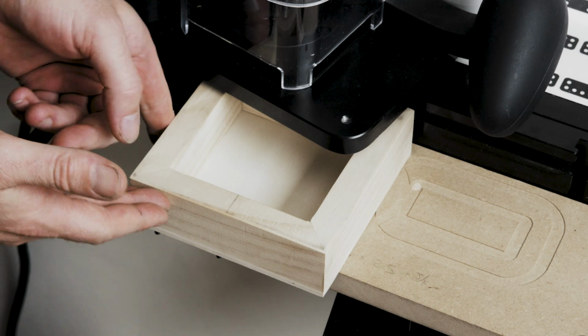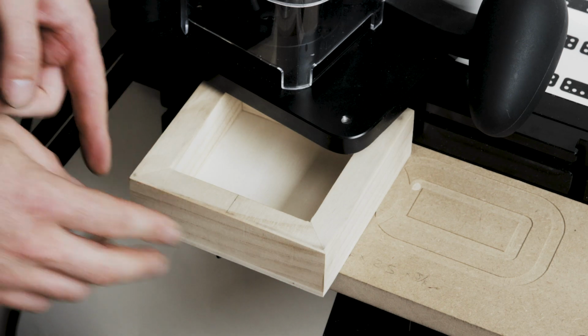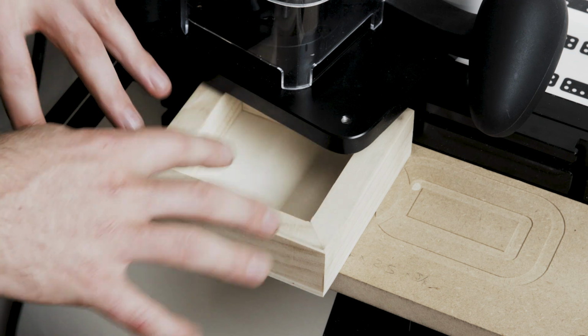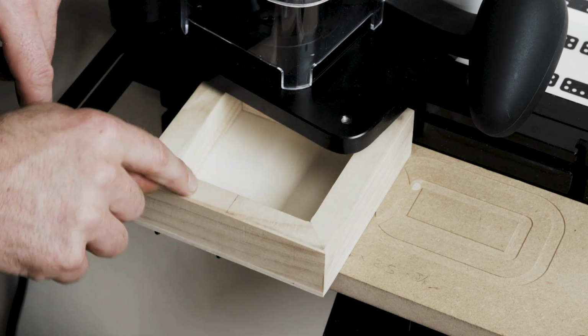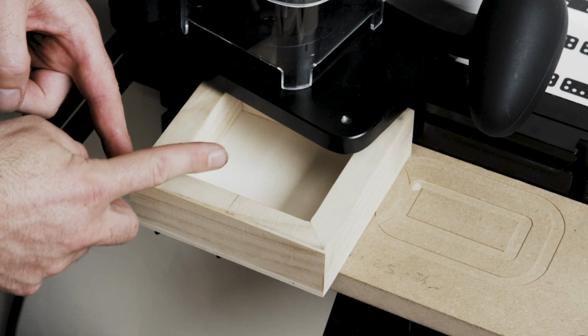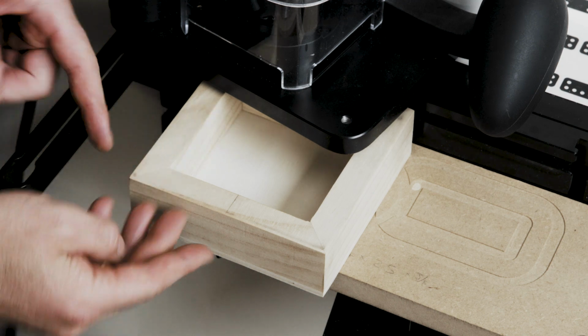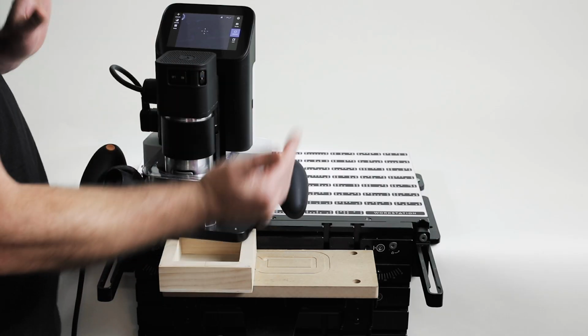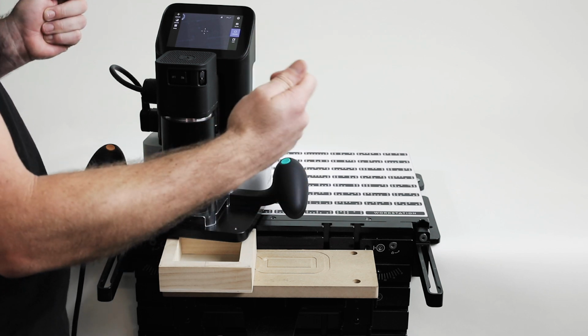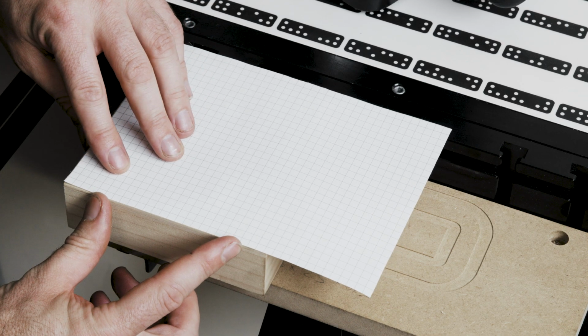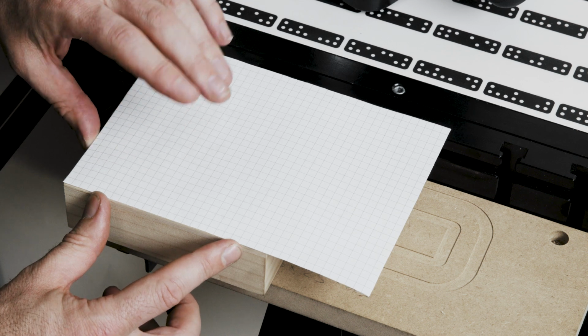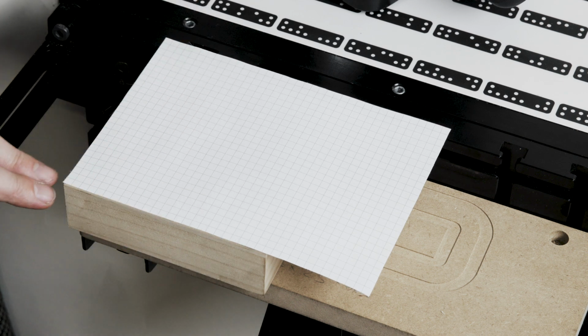The next step is that Origin has no idea of where it is relative to the edge of stock. Often we're going to want to place a shape exactly centered on the top or an inch in from these two edges. So the gridding process is taking effectively a grid, think of gridding paper, and aligning it to two edges of this. One edge will be the x-axis, one edge will be the y-axis.